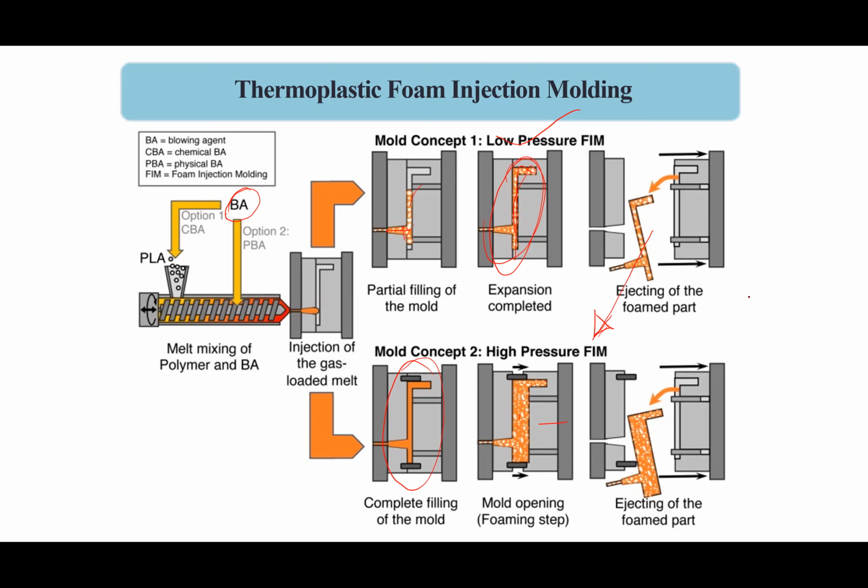You can squeeze them to a flat plate, and then when you release it, it gets expanded. What happens is that the gas formed due to the blowing reaction of the blowing agent is compressed in here. That's why you don't see the voids. But once the material is cured and you remove the mold, it is expanded, and then you get the final product.